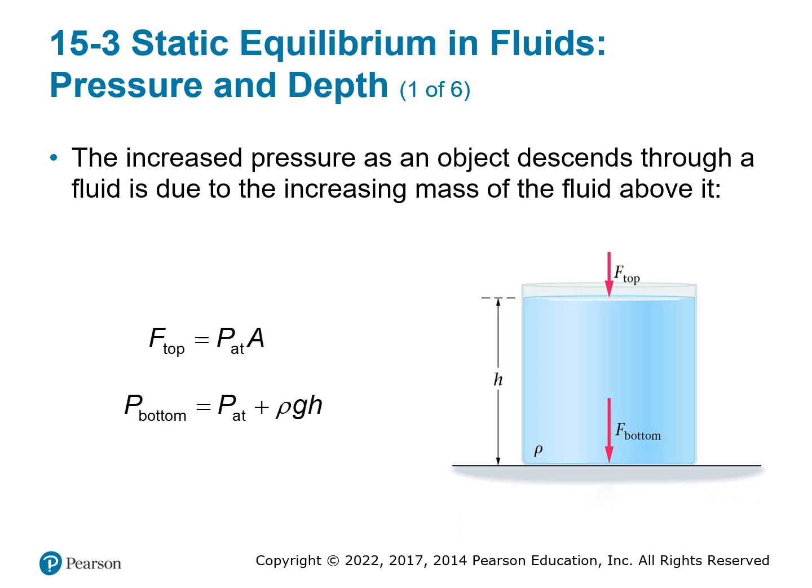So you are taking into account the atmospheric pressure plus everything else that is on top of it. And this equation here is the pressure with a certain density of the fluid. So atmospheric pressure, plus pressure due to the fluid. Add them together, and you get the total pressure at the bottom of the fluid.